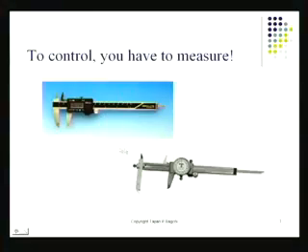So you've made sure that these instruments which I'm going to be using here, these are the instruments that, by the way, measure dimensions. You've got to make sure they've been calibrated, and also we know exactly if they have any drift or anything like that. So gauge R&R is the variability that is introduced by using the gauge as a measuring device, as something to produce data. That has its own contribution to variation in the ultimate data, and it is kept within a very tight tolerance.